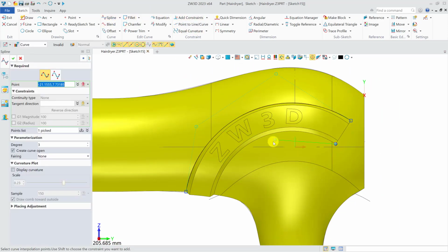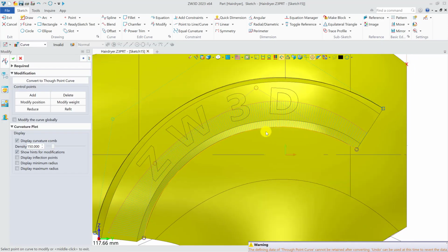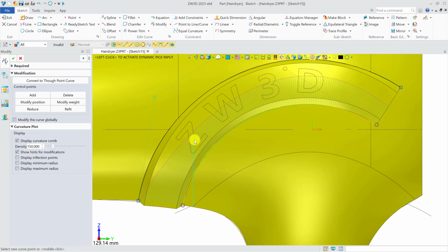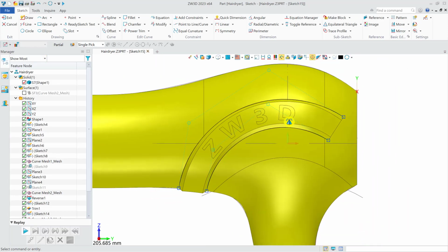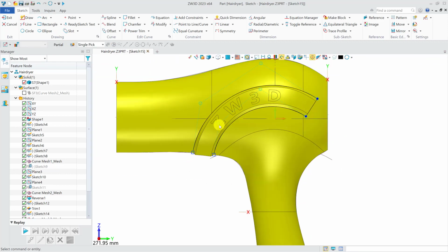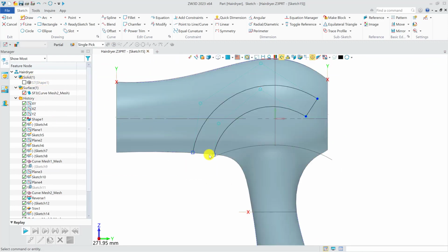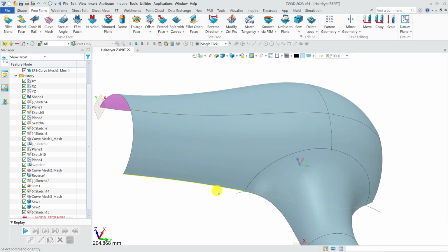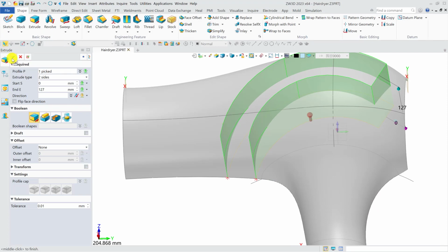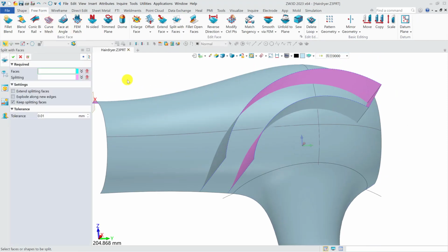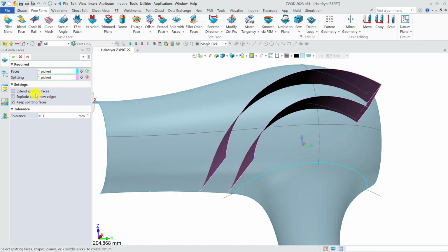The operation of the other one is the same as the first one. You can see, the core of product design is to draw and adjust the spline. Create a connected line. Extrude this sketch to be a surface, and then use the split with face command to split the surface.